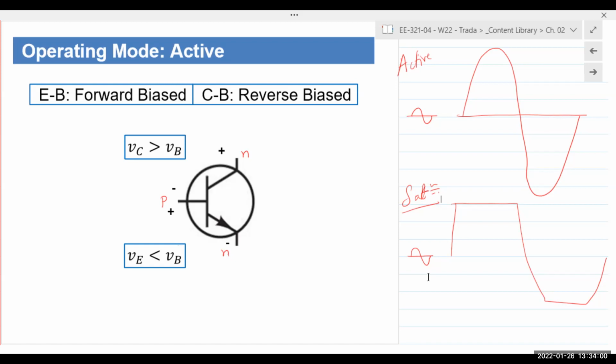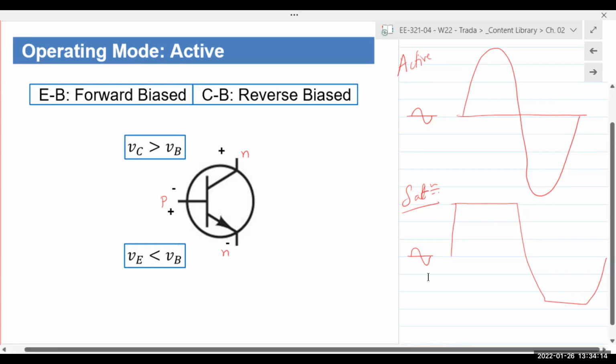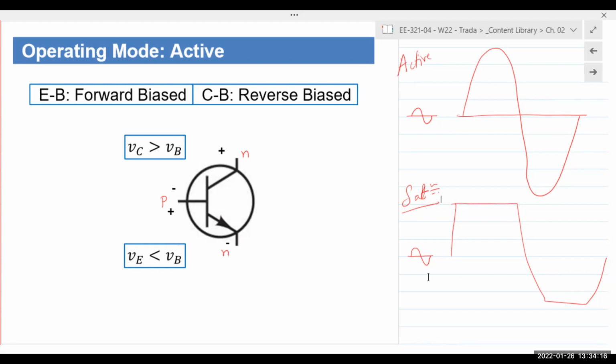Well, the energy to make it bigger does not come from that AC signal. It comes from the DC bias that we apply. So you have an AC signal coming in and a DC biasing that we apply to that amplifier. Does that make sense? So it's a DC voltage and current that is being applied externally. What your amplifier is doing is it takes that DC and that AC and gives the shape of that AC signal to this DC voltage that's coming in. So now your DC, which was a flat line, takes the shape of the AC signal.